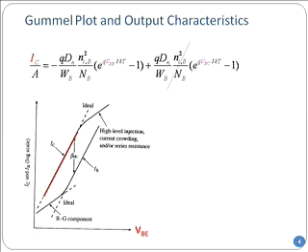Now what about the base current? Well, from the previous slide, you can also calculate the base current, and correspondingly the base current will also depend on V_BE, because as soon as you forward bias a base emitter junction, electrons go up easily, and the holes also go to the emitter easily, and so therefore they will have the same dependence on the base emitter voltage.